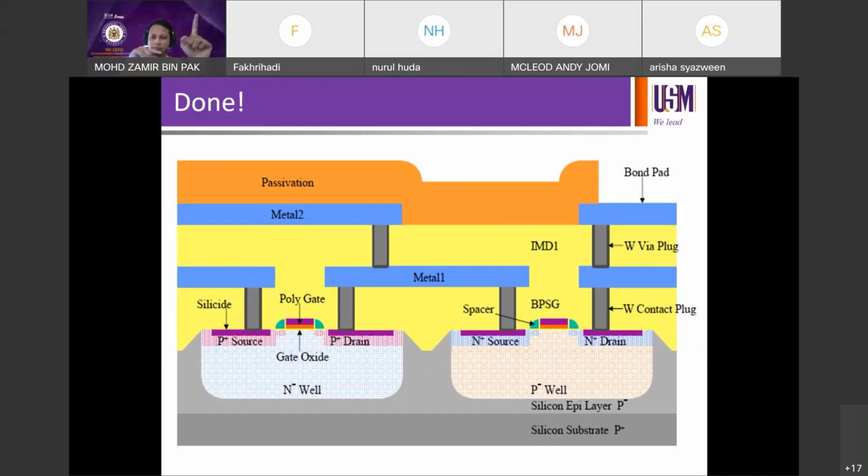They will see, oh, this one uses a different tungsten plug material, the position is different, this one uses another metal, and this litho is not that complicated, this one is more complicated. So when you have all this foundation, wherever you go in industry, it will be similar except for the details, like the flow and the process. But the foundation is the same. Patterning, litho first, then etch, then whether to diffuse or implant. That depends on the device and the industry and many more things. But if you have this basic, wherever you go in industry, it's pretty much the same.